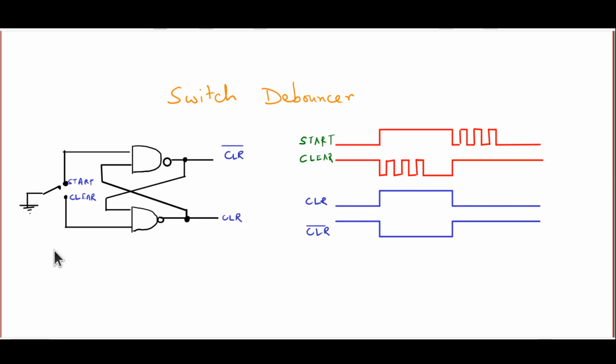Now, one of the most common kinds of gates that we have use what is called TTL, transistor-transistor logic. We are not going to go into the details of that in this class simply because we don't have the time to do that. But one important point about TTL logic is this. If an input is floating in a gate which works on the basis of TTL logic, then that input essentially is high. So floating means high. This is what you have to remember.